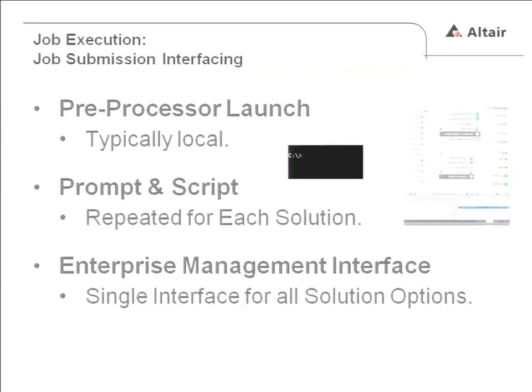Once we know what we want to do, once we have our model built and we want to hit go, it's really nice if you could do a pre-processor launch. What that means is there's some other application that you're using to set up your model, and it would be really nice for everything to be a black box: push a button and it runs in the background, you never see it run, and you get your answer and you look at it. That works really well if you're working with a smaller model and it's local or a test model, but once your computer can't handle that and you have to go to HPC, that really isn't an option anymore.